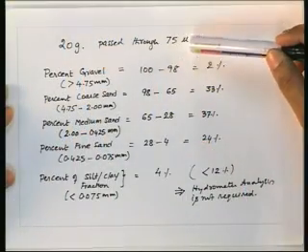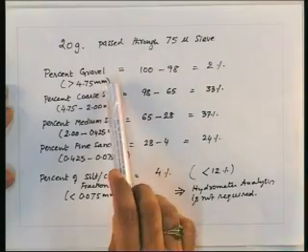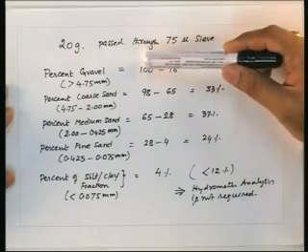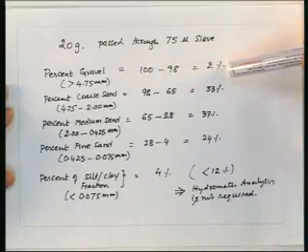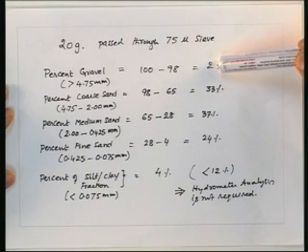Once we have this distribution, we can determine the gradation. We have seen in the previous example that only 20 grams of the soil passed through the 75 micron sieve. So, this gives us the percentage gravel in the soil matrix, which is greater than 4.75 mm: 100 minus 98 is 2%. That is, 2% of the soil mass taken represents gravel size particles.